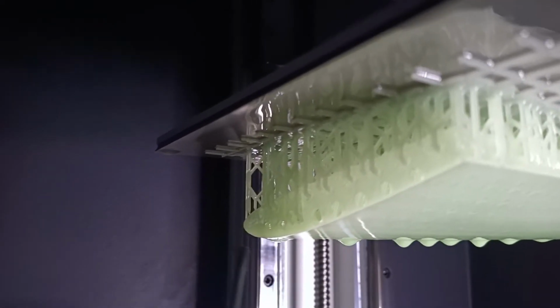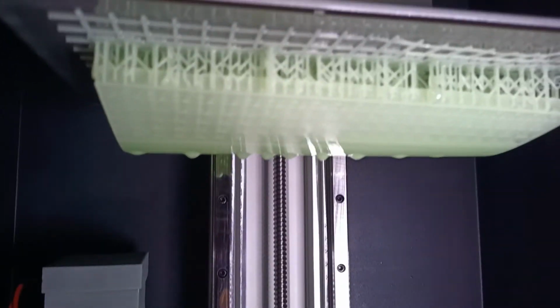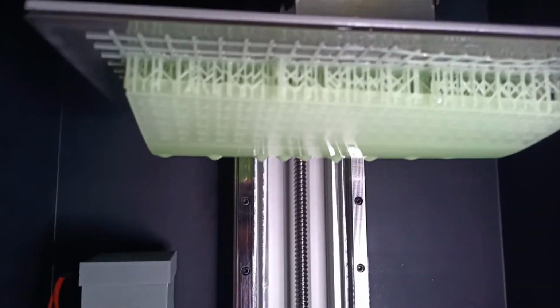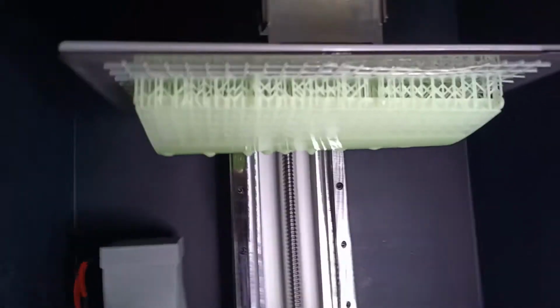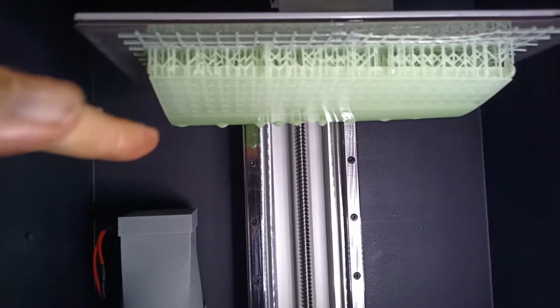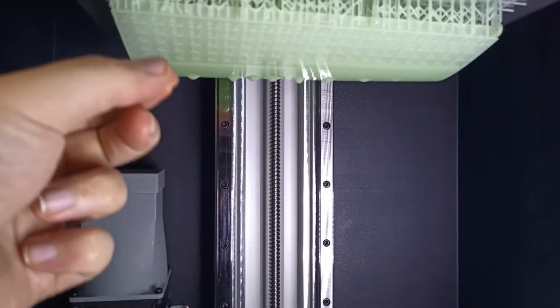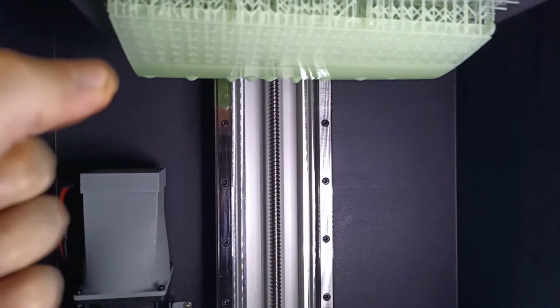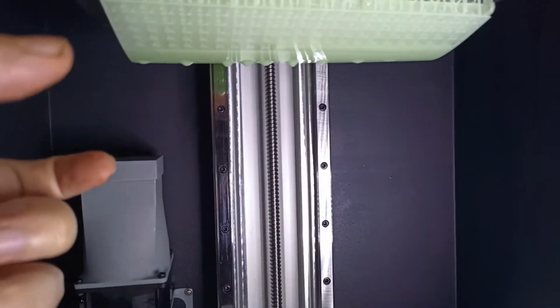Now, all along the side are holes. See all these holes here? This is where all the resin drains out of, all of those holes. And that's on both sides. And this part, that leading edge on the top surface there is quite flat. And this is because I wanted to get better printing from the layer, so that more of the layer is exposed rather than just that 0.5 millimeter. This is part of the reason for why we've gone to this much more flat orientation, is because I get more of a layer exposure rather than a very thin slit of where the skin is. The skin is cut at an angle through the layer, and you get a larger exposure, you get better exposure.